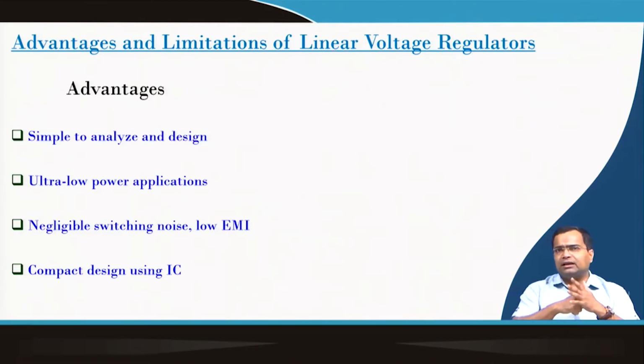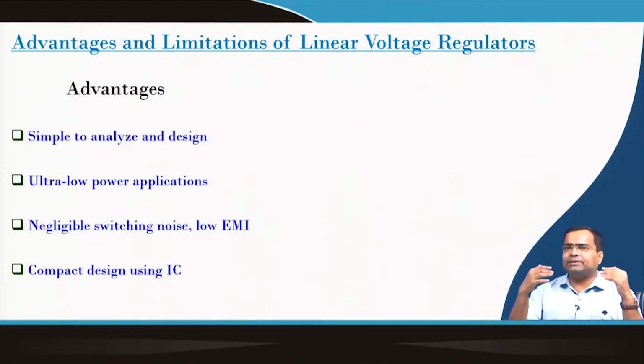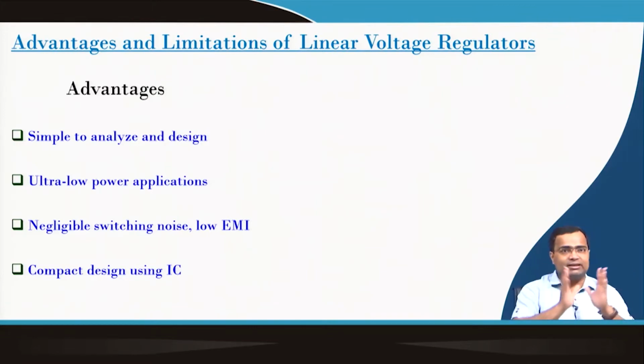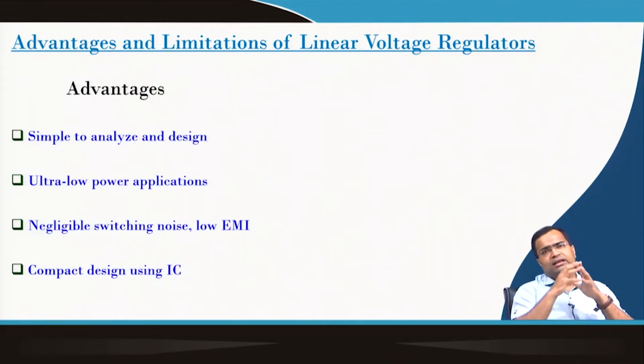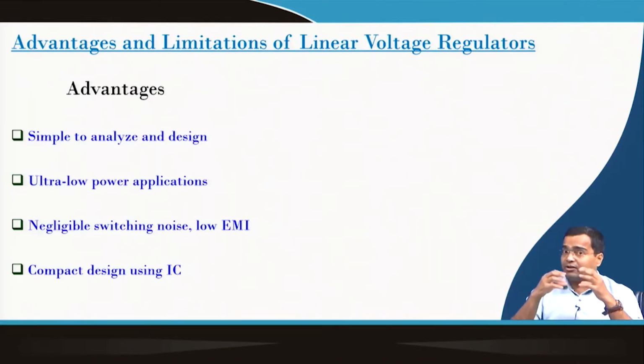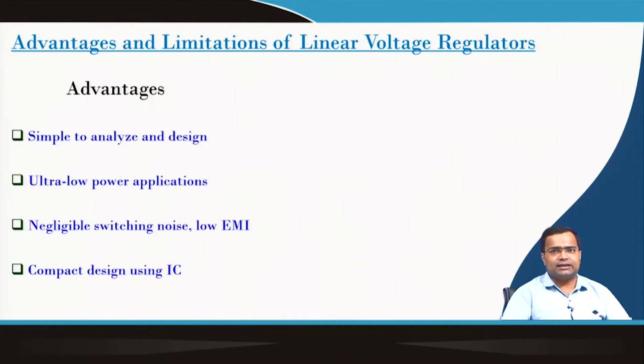It also has negligible switching noise, because there is not much switching, unlike the subsequent voltage regulators we will be discussing, where there will be inherent switching. So, here it is less susceptible to switching noise. As a result the EMI is low, and also the design can be made compact using an integrated circuit.